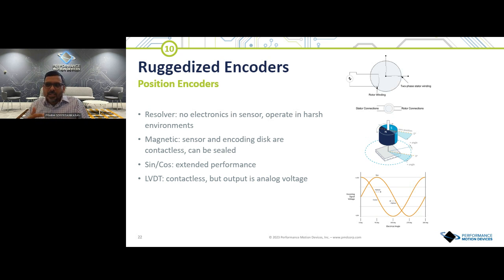And we have absolute encoders. You're starting to see more of them with newer interfaces, like BiSS serial. It used to be SSI, and now there's BiSS and newer serial topologies where you can daisy chain multiple encoders. And we've also seen people using multiple encoders for safety.